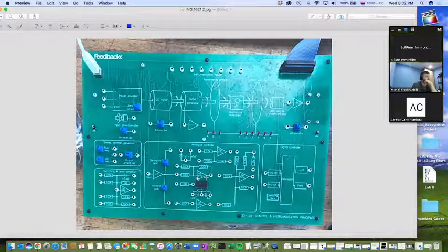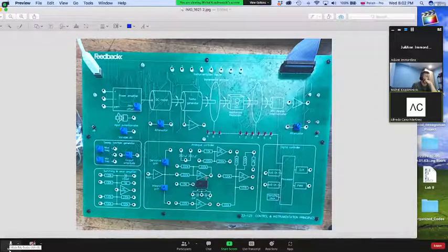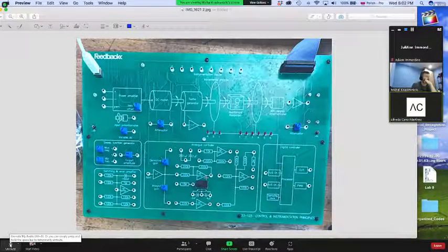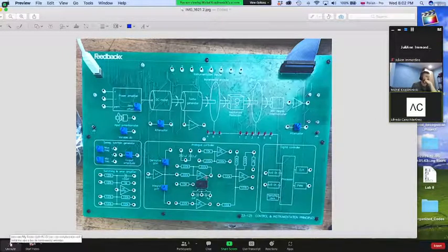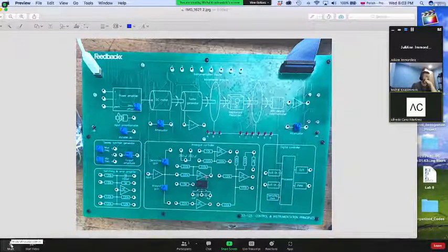Yeah, usually in most circuits, the most effective signal, without worrying about performance indices, is the proportional signal. So almost always, except in pathological cases or in really sophisticated circuits that rely on some other kind of theory, you should see some kind of proportional channel or signal or gain in your feedback system. This applies even to really sophisticated feedback algorithms.